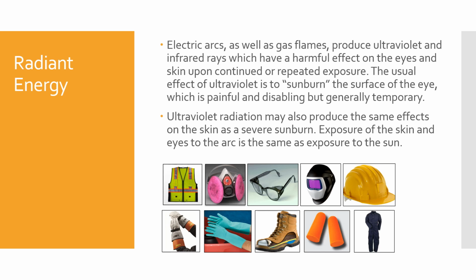So radiant energy comes off the electric arc. You can get sunburned by this. It can damage your eyes. So that's why you always want to wear, you'll see welders, it'll be 900 degrees outside, and they will wear a long sleeve shirt, and they'll usually have it buttoned up. I worked at one place where the welders would put sunscreen on the back of their neck because there was some flash that would come off and get them from behind due to the shiny ceilings or whatever.